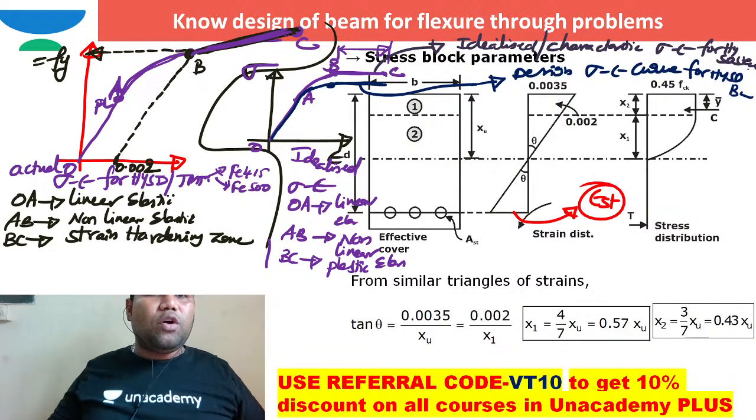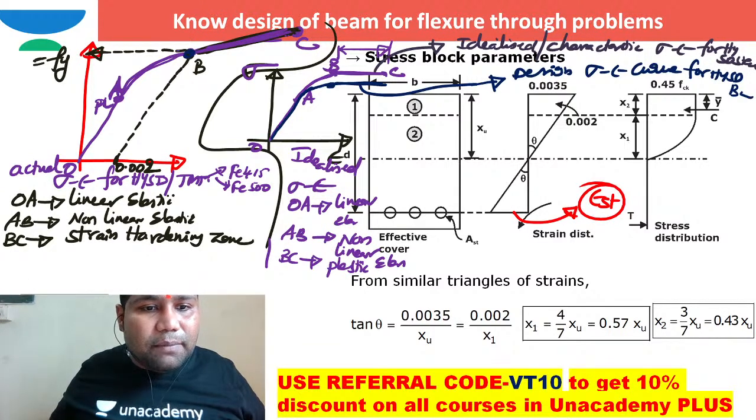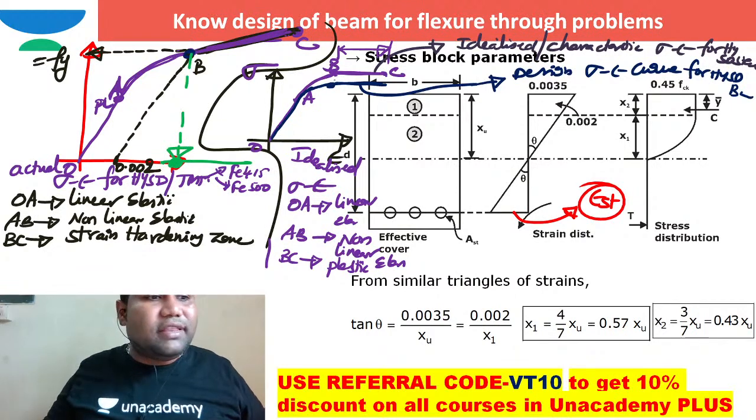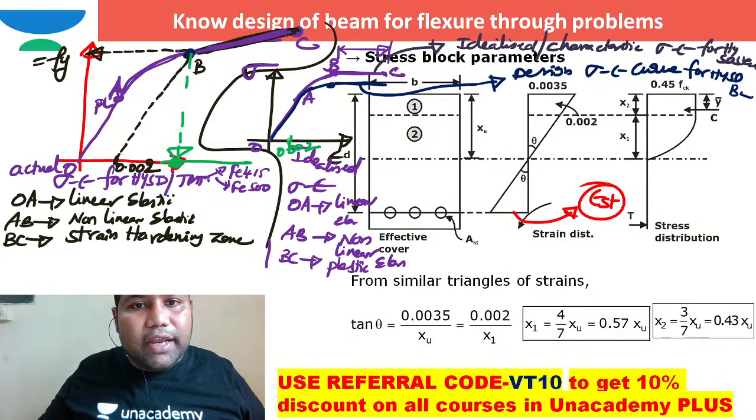In this case, I hope you know at B what the strain is where it is failing. At B, it is failing at that time. What is the strain in steel? The strain in steel at that time is called the failure strain. But I need to draw a line from this point to B. This stress is nothing but the design stress.